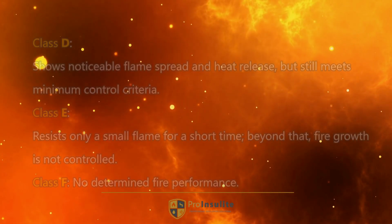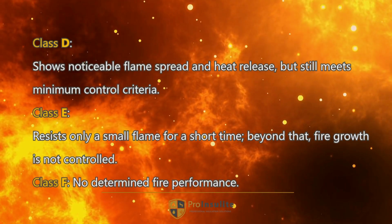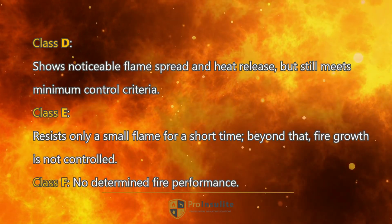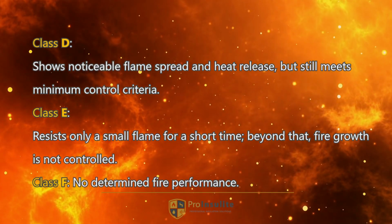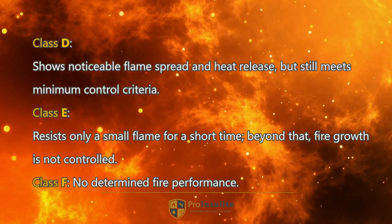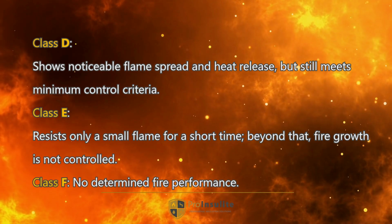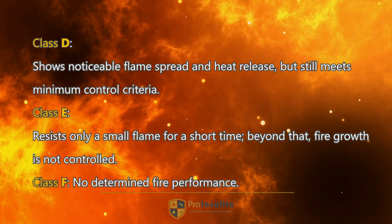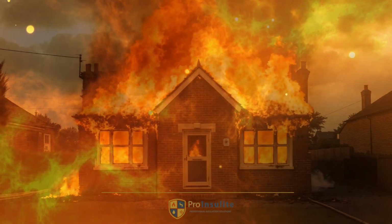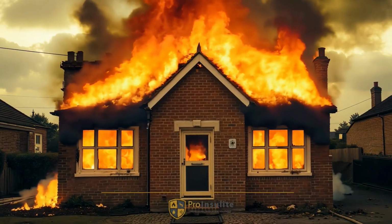Class D reflects acceptable fire performance with a more noticeable contribution to fire. Examples may include untreated wood-based panels and certain plastic products. Class E indicates basic reaction to fire behavior. These products resist only small flame exposure for a short duration. Class F signifies that no reaction to fire performance has been determined. However, fire risk is not defined by ignition alone.